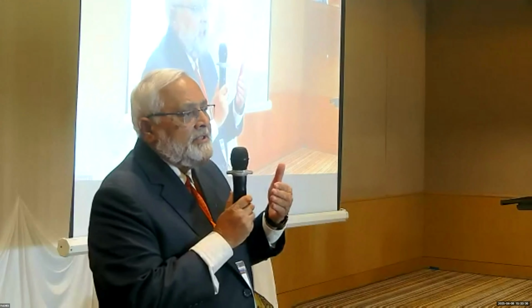Immediate occupancy is for a facility where you would not like any structural damage and which should be ready for use right after the earthquake. But it's not that simple, unfortunately, because you have to look at the non-structural elements also. A hospital building may be safe, but if the oxygen pipeline breaks, or if the refrigerators storing blood topple over, or if the electricity or the water supply breaks down, then the building is of no use. So we have to look at the whole thing on a much larger scale.